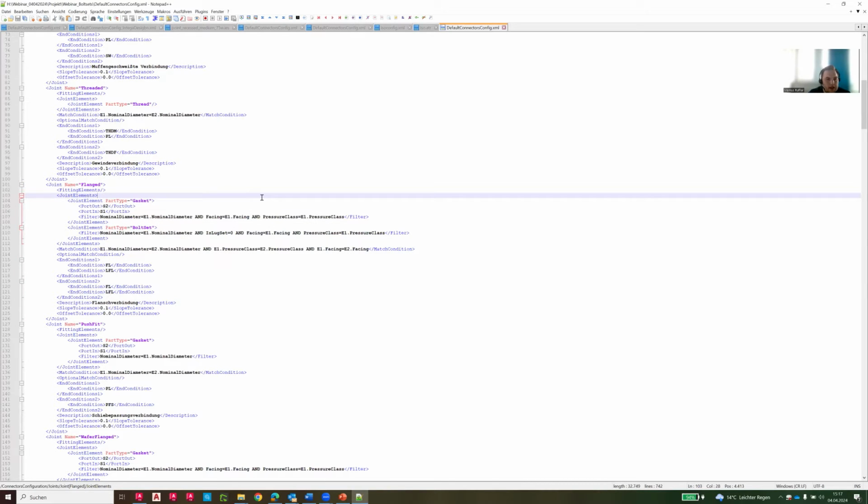So, now how can we add new bolt sets there? It's pretty simple, but please keep in mind, you can only do this change in that file. If you later open your flange connection through the flange connection settings in the user interface, this will be overwritten to one bolt set again. So keep that in mind if you need to do some modifications later on this flange type.